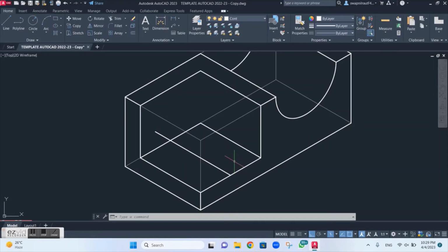So again I need to use the isocircle command. So for that I will first activate the ellipse. So EL, enter, and I, enter. I repeat it again, EL, enter, I, enter. Specify the center. Okay, so just wait, I need to draw this accurately first.